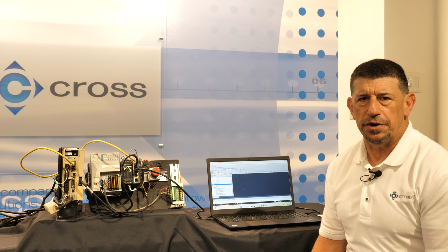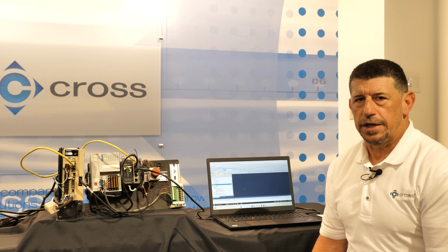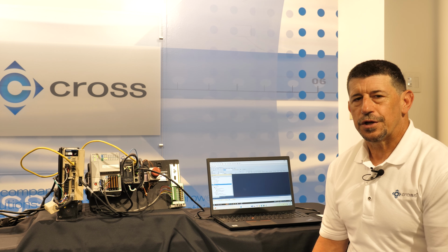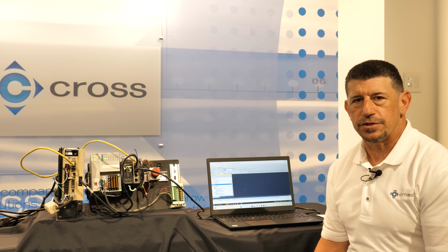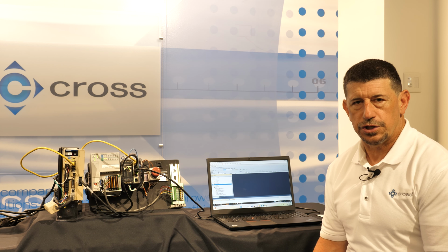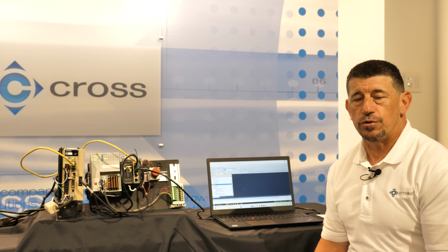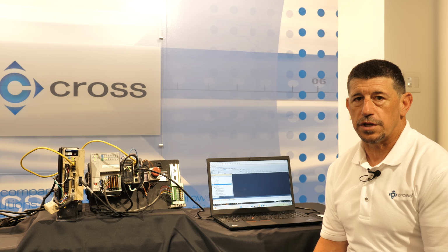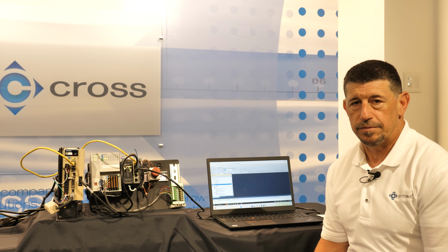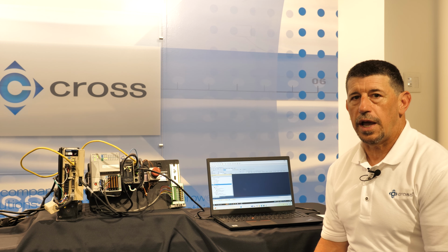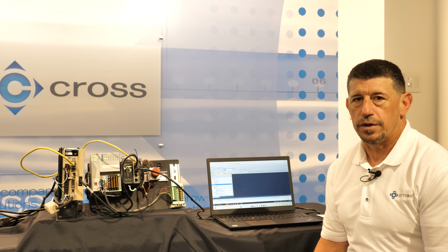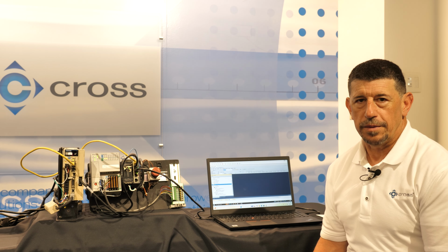In this segment of the series, I'm going to be demonstrating how simple it is to go to the Yaskawa website, download the necessary files, including the add-on instructions, import those add-on instructions into the RSLogix 5000 software, pull those instructions into your program to create a very simple, straightforward motion control program.